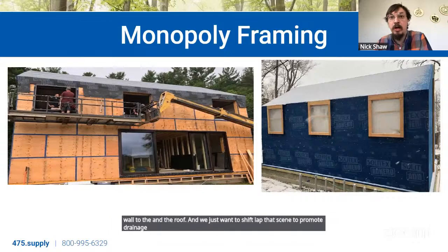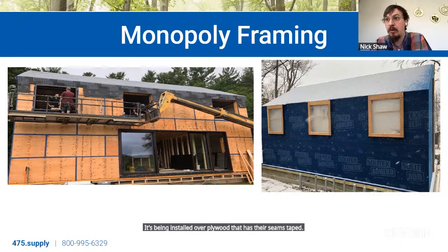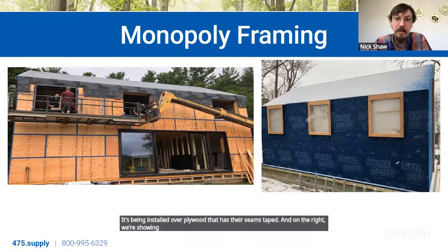So on the left here, you can see the Menta 1000 membrane. It's being installed over plywood that has the seams taped. And on the right, we're showing the Solitex Adhero membrane, the peel and stick membrane, the fully adhered version.